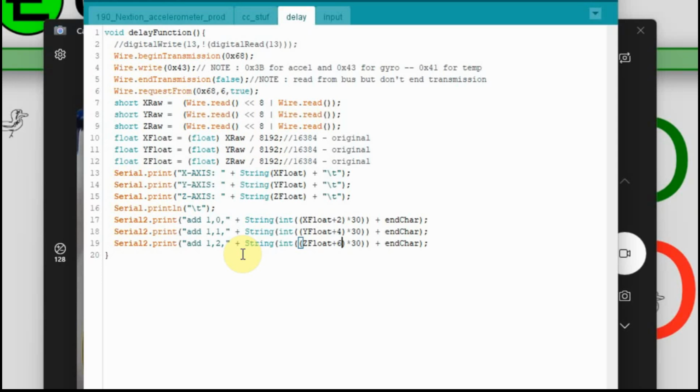And you do that by setting up the number of channels on the Nextion before you start transmitting data from the Arduino. And as I said at the beginning, that's one of the things I get wrong a lot, and I have to go back through and redo, because I'll be sending 3 channels and go, oops, I'm only seeing 1, I know what it is now. So I just go back to the Nextion, reload it, download the code, and I'm good to go.